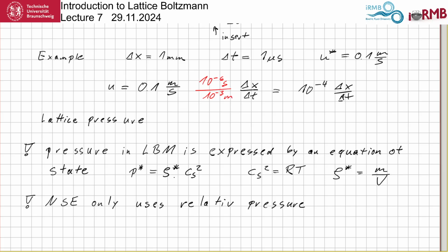Now we come a little bit from kinetic theory, and in kinetic theory, if pressure is zero, you are in a vacuum. Right? So if you initialize your pressure in Lattice Boltzmann with zero, because this is what you do in your Navier-Stokes solver, crash. Yeah? That doesn't work.